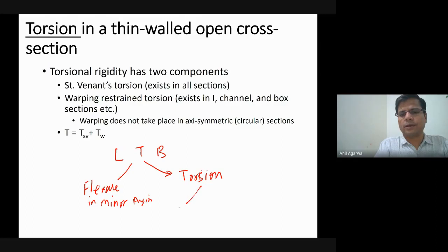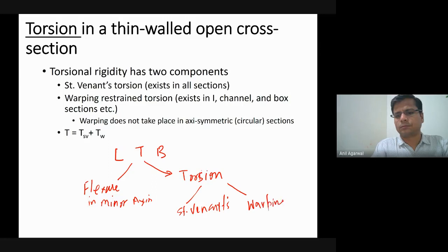Now within torsion, you have Saint-Venant torsion and you have warping restraint torsion, a warping torsion. Okay. Now, I'm not so sure whether you have heard of these two terms, Saint-Venant torsion. Also, it is known as pure torsion. Pure torsion. Okay, and then warping.